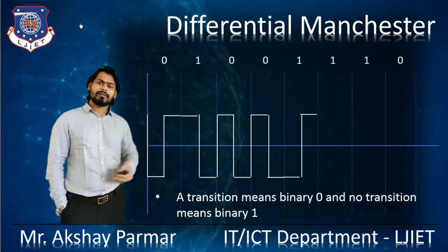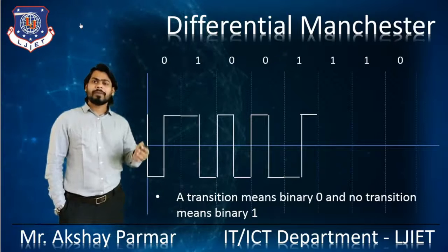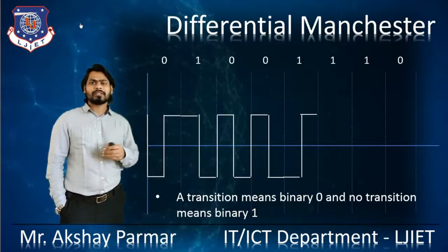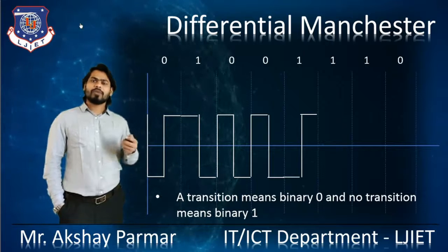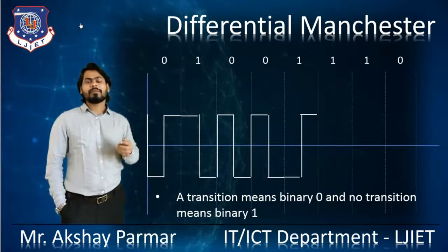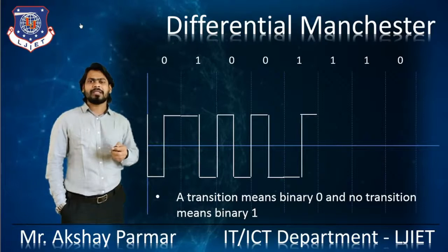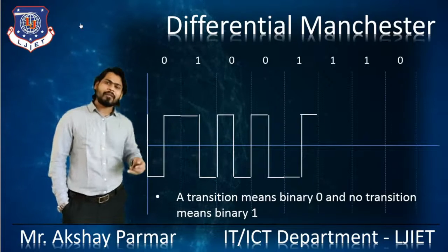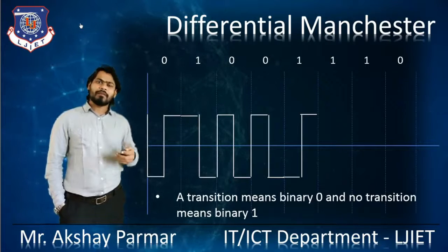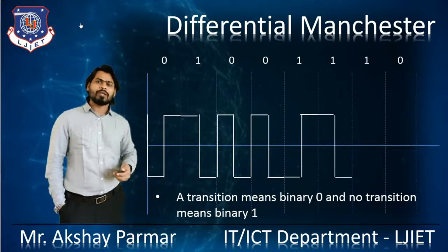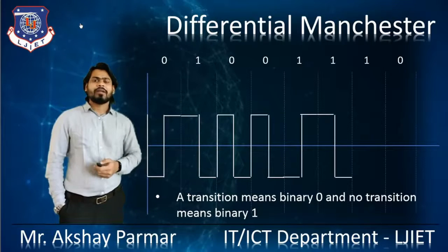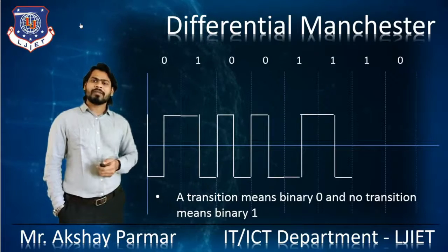After that, the bit 1 is there again. To represent that bit 1, we will use the inversion of the previous transition, right? The previous bit is represented by the negative voltage to the positive voltage, so to represent that bit, we will follow the positive voltage to the negative voltage. After that, the third occurrence of the bit 1 is there.